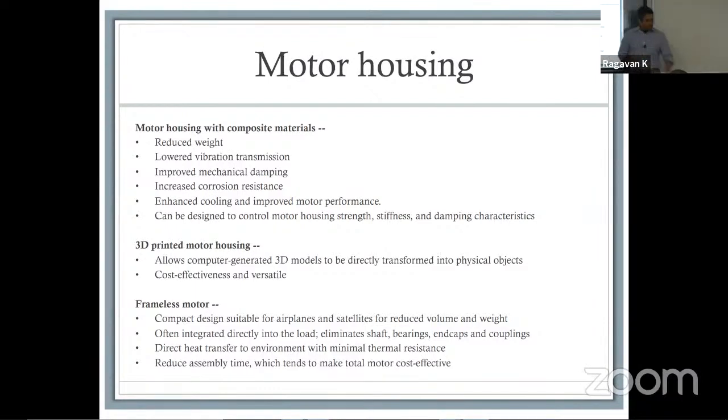In that case, you might look specifically at composite materials, which can have resistance to corrosion for ambient conditions. You're deploying it in a place where you're going to have a lot of dust, offshore wind, for example. You might be looking at a boat application where you're going to have a lot of saltwater spray happening. Corrosion can be a very big problem. In cases like that, something like this might be relevant.